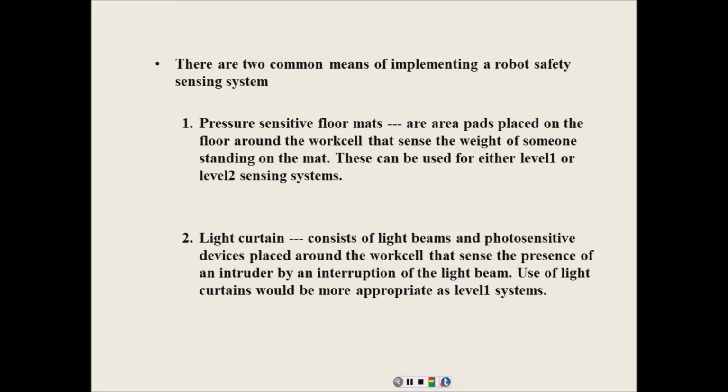And plus you can use mirrors. The only problem we have with these: if you're operating them in a really dirty environment, you need to clean them off, because all of a sudden it'll say somebody is there when there's not really anyone there, because something has screwed up your light curtain or got in the way. So these things are susceptible to dirt and moisture.